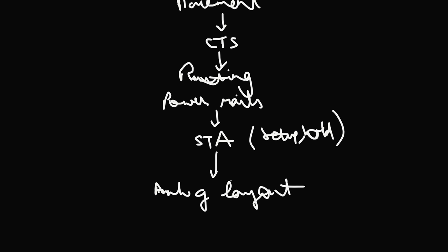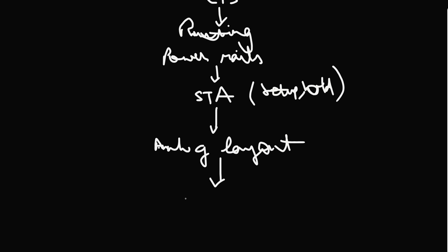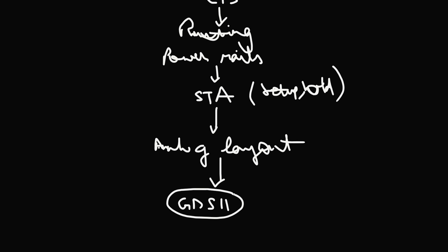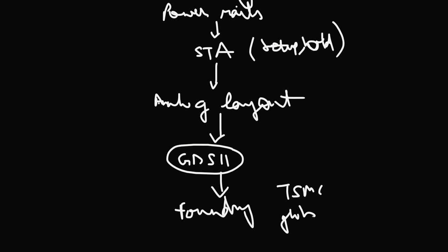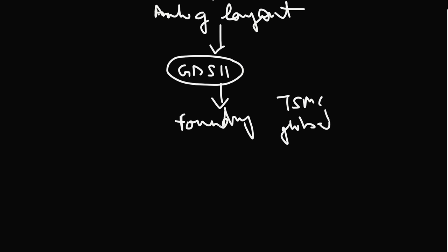Based on this, we get a complete blueprint, the GDS2 file. Once we are done with the layout stage, we get a blueprint or a GDS2 file, which then goes to the foundries which I mentioned earlier, like TSMC, Global Foundry, etc. Then the chip gets manufactured by these foundries. We book a slot here and get the chip manufactured.